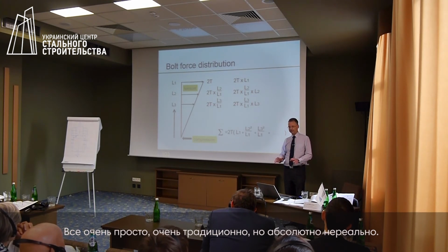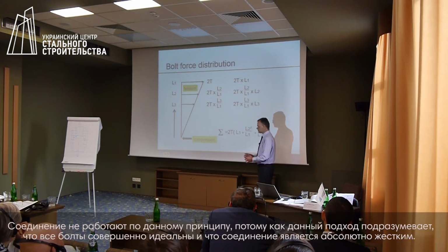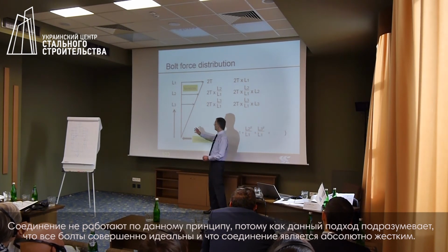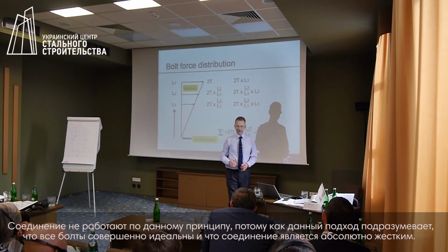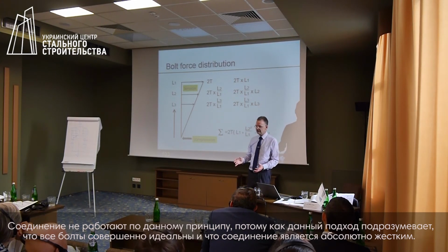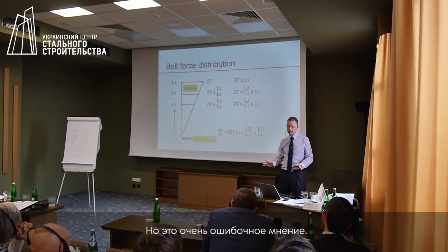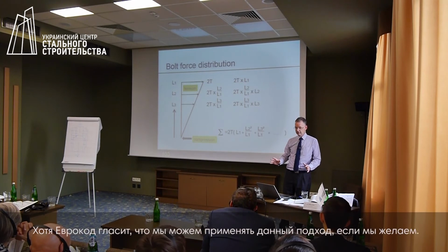absolutely unreal. Connections do not behave in this way because this presumes that all the bolts are perfect springs and presumes that the rest of the connection is entirely rigid. And that's completely wrong. The Eurocode says we can do it if we wish.